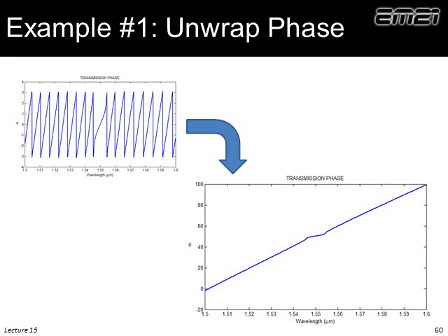In fact, the discrete jumps you see aren't really happening. Think this way. We have phase that's increasing, increasing, increasing. When we get up to pi, remember, we've bounded our phase from negative pi to pi. So it doesn't make sense for it to keep increasing. In reality, it does. So we jump down by 2 pi, and we keep increasing, increasing, increasing, jump down by 2 pi. So there's what's called wrapping that's happening here. And we can unwrap this, and maybe it makes a little more sense.